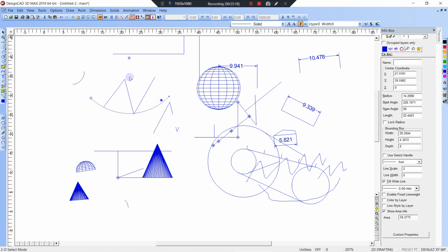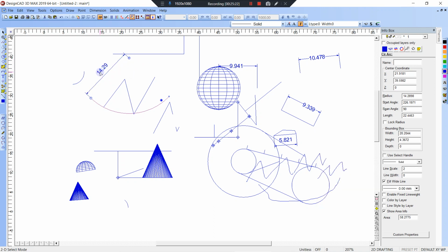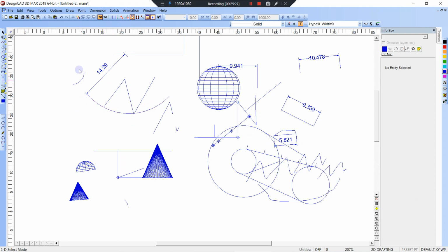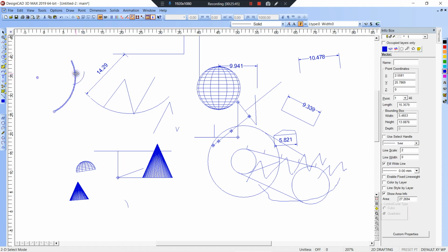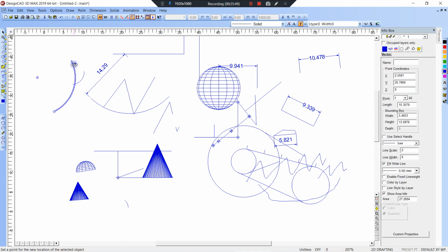So arc here to here, and why is the radius fixed, F3? Because it's fixed at a 120 degree angle. So I could change 120 segments. 45, enter. Yeah, not sure what that does. That drew it as a line. And a line is a vector entity.